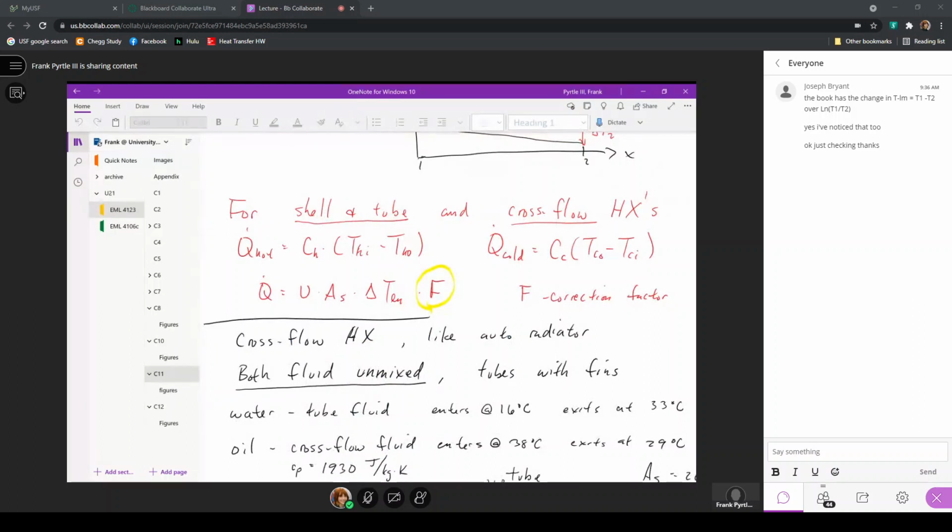And through this expression we're able to find, let's say, what the overall heat transfer coefficient would be, or what the shared surface area for heat exchange has to be in a given heat exchanger if we have some temperatures that are given and the temperatures that are required. So the log mean temperature difference method is defined according to how we relate the actual heat transfer occurring between the hot and cold fluids with regard to the geometry of the actual heat exchanger.